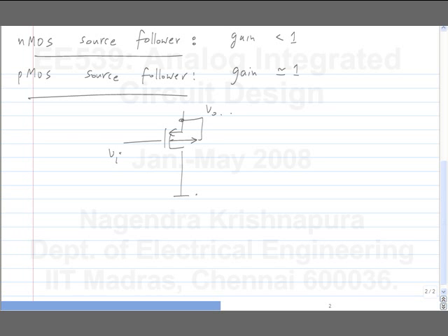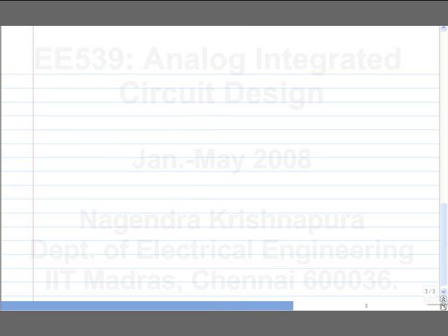So the DC analysis is quite simple. Now, the AC picture can be analyzed by adding all the parasitic capacitors. I will ignore the bulk transconductance, and when it is there, you can add it to GDS. It always appears as a conductance in parallel with GDS.